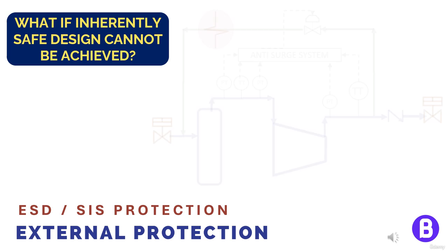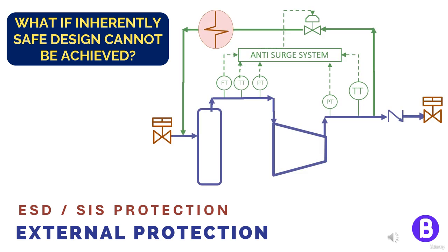For example, when we talked about recycling the gas from the compressor discharge to the compressor suction while the recycle or surge cooler is down, this shall cause the compressor to compress the hot gas and the temperature shall increase drastically. This shall even cause more severe issues in reciprocating compressors. Here, we cannot consider a design temperature that guarantees this situation. That's why we should find another way to face this scenario.